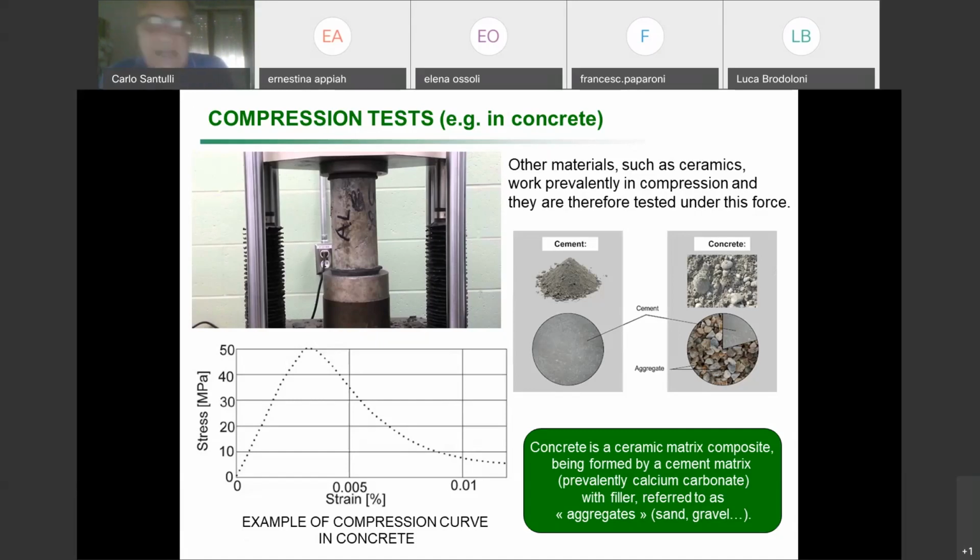I will carry on talking on that later on, but when you say visco, that means it's sort of elastic, but it depends on time. Time has an influence. If a material is elastic, it's fully and really elastic. It doesn't make any difference if I pull it quickly or slowly.